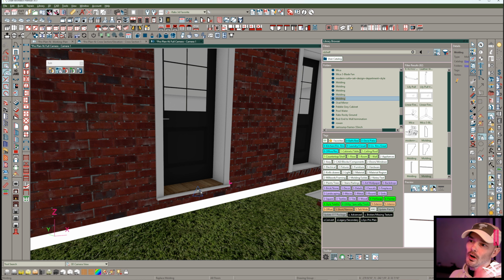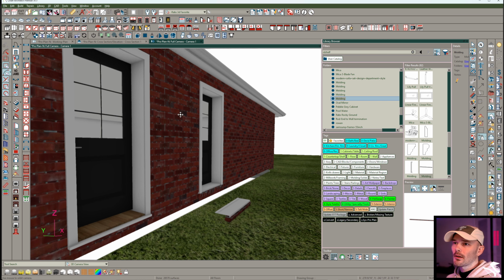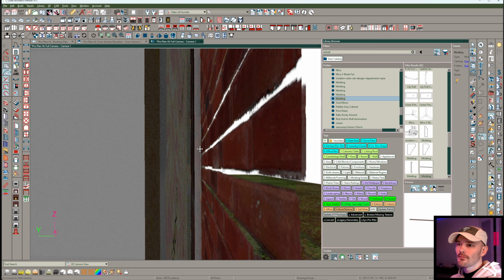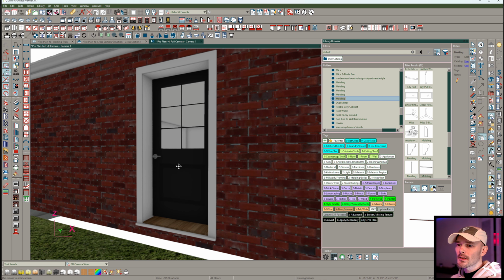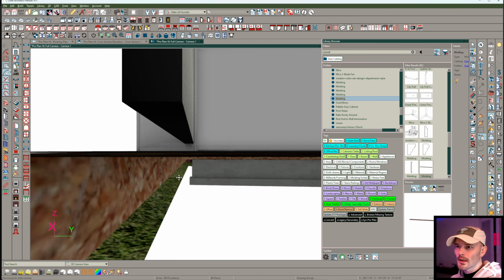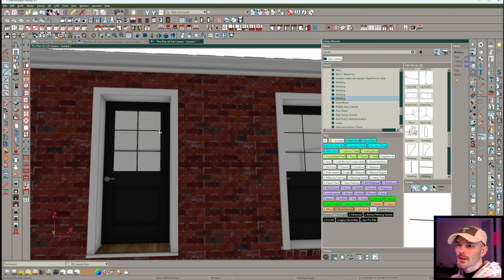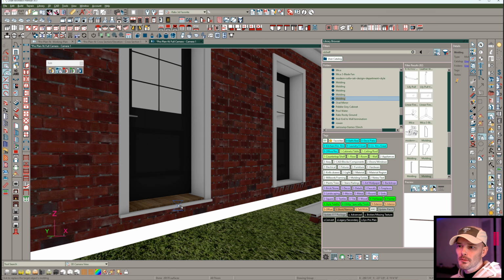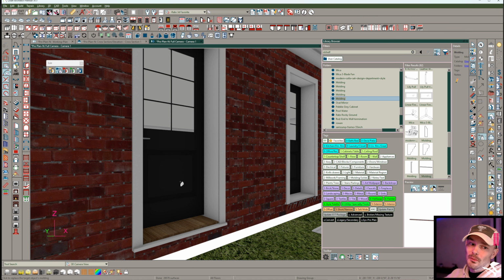Now this is kind of common, there might be some other classification of millwork in this symbol, because I don't think this generated anything. When there's some other classification of millwork in a particular symbol, even though the toggle replacement mode is there, it might be replacing something that takes precedence.